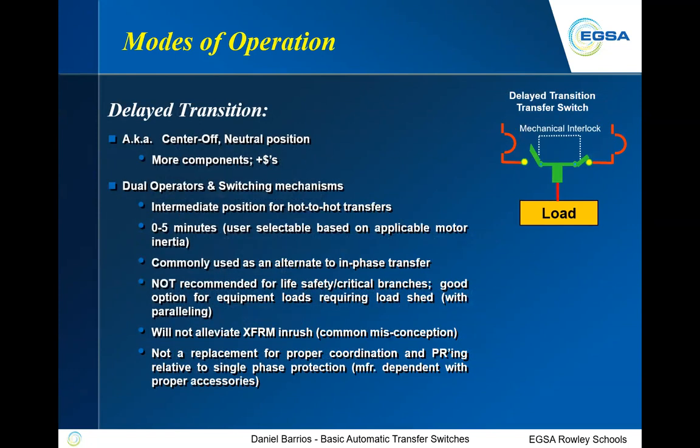Now, when you go to a delay transition switch, obviously as I've made the other comments, there is a center off, neutral position. There are more components. Now you have two operators to operate the normal set of contacts and the emergency set of contacts independent of each other. There is an intermediate position even on a hot to hot, and that is, as I say, for the back EMF to wind down.